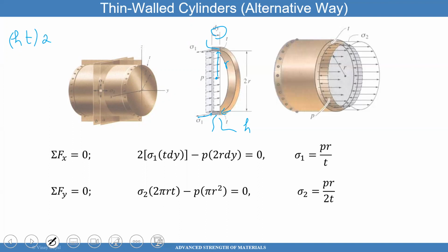And then I have a stress associated with that, sigma 1, acting on those little rectangles. You can see the sigma 1 right there. Then I have that pressure acting on this projected area here. That projected area is minus P times what?